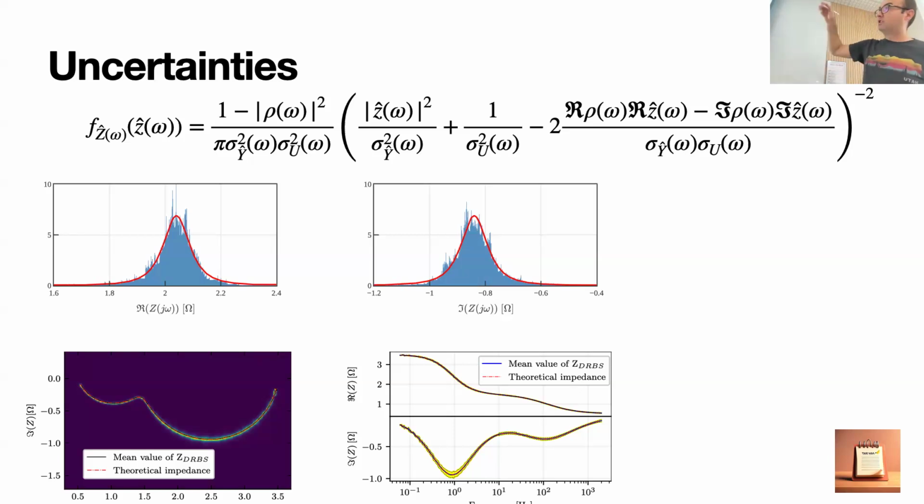And the blue dots are our measurements. The red line is the actual fit of the above formula. And now we have the distribution for each of the impedances, and we can actually draw it here as a confidence interval. There are intervals where we are less confident because of low frequencies, bigger noise or whatever, and there are intervals where we are more confident.